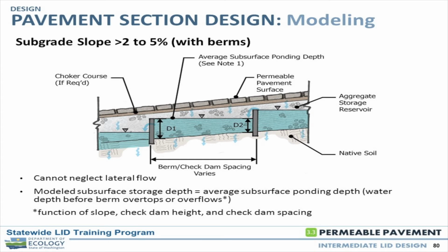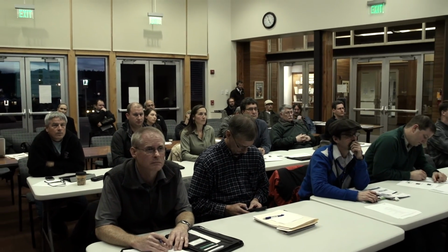Or if our geotech tells us that we only can get a relatively small infiltration rate, and we decide that we're just going to use that permeable pavement for water quality treatment, and so we're just going to infiltrate 91% in that area, and then we're going to route the overflow to a flow control facility. Anyway, we can optimize that situation by looking at the geometry there and then setting the depth of our base rock to achieve whatever criteria we're trying to meet.